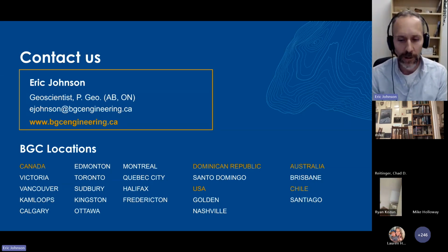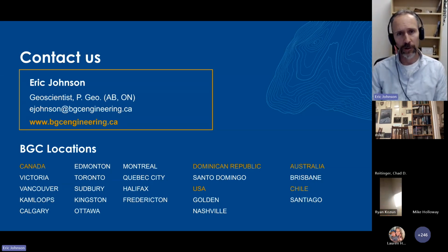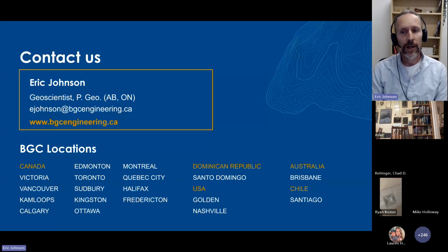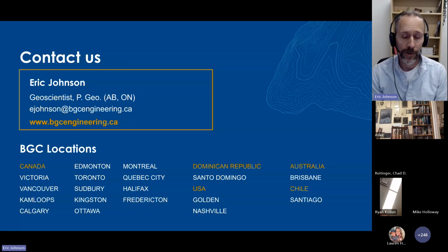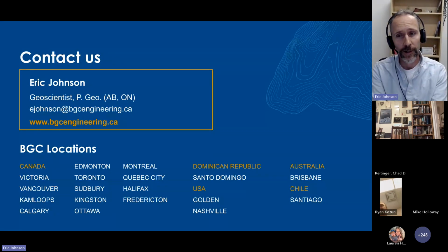It's something that we do already anyway. When we go to a brand new site, we're already expecting a certain range of values for clay. And that's how we interpret data in sites with no boreholes. But now we can do it quantitatively and with more confidence with this method.